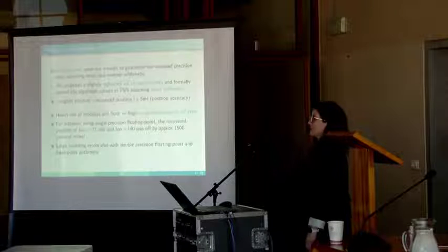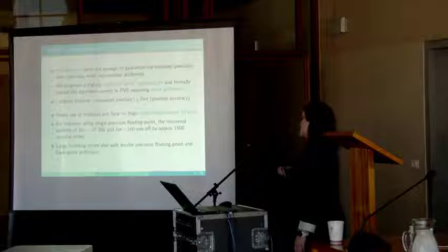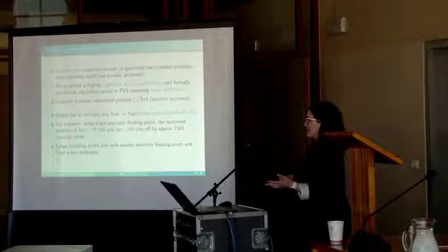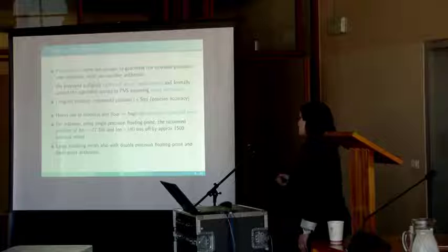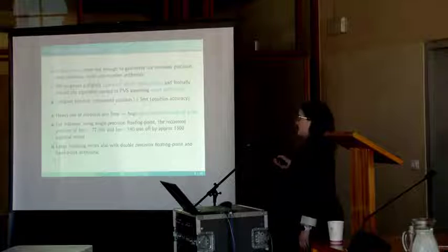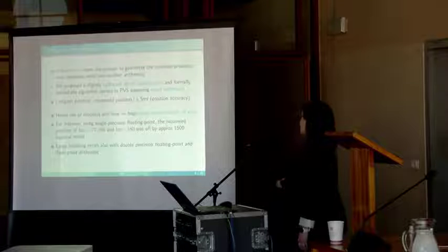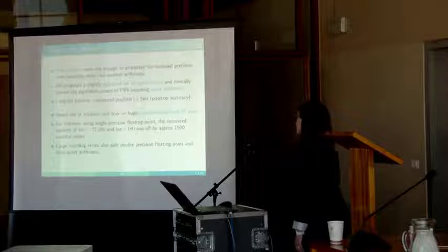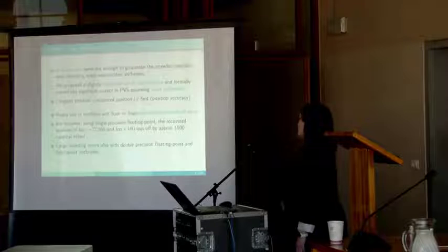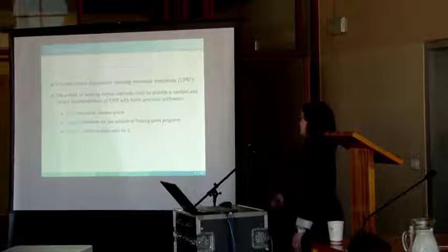And this is because CPR makes heavy use of the modulus and floor functions, which are intrinsically unstable. For instance, we had a test case where, using single precision, the CPR algorithm was off by 1,500 nautical miles. And we also found other test cases with double precision and also fixed-point arithmetic.